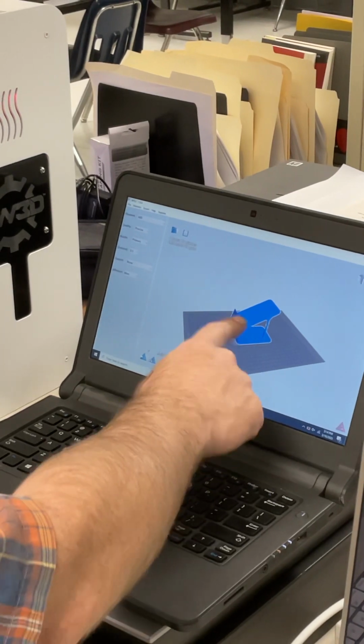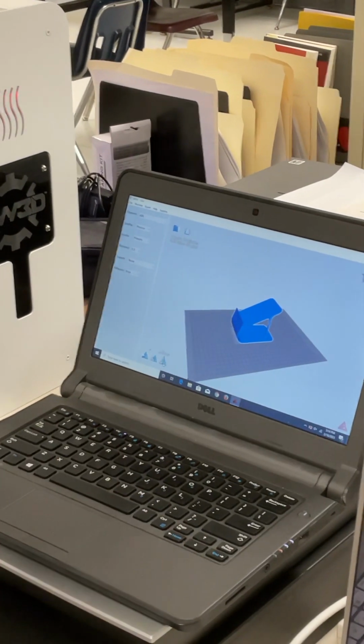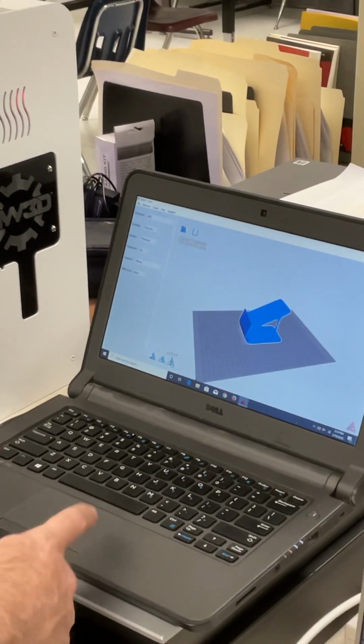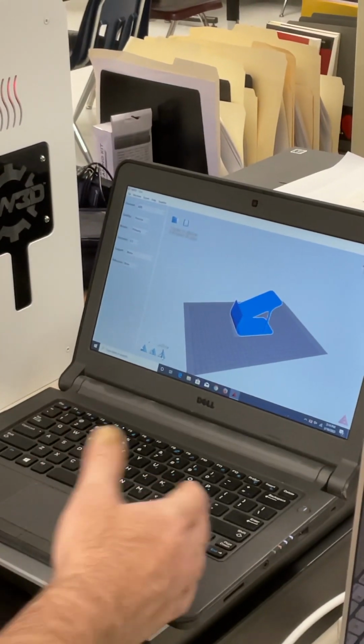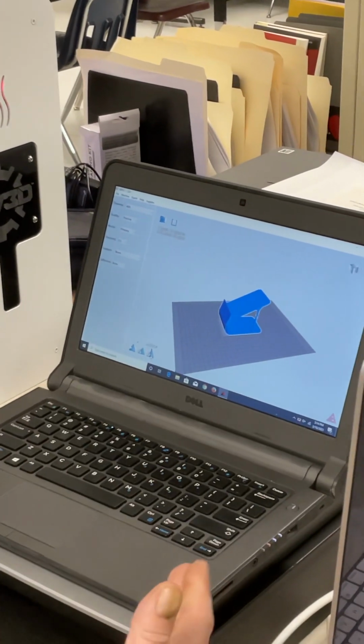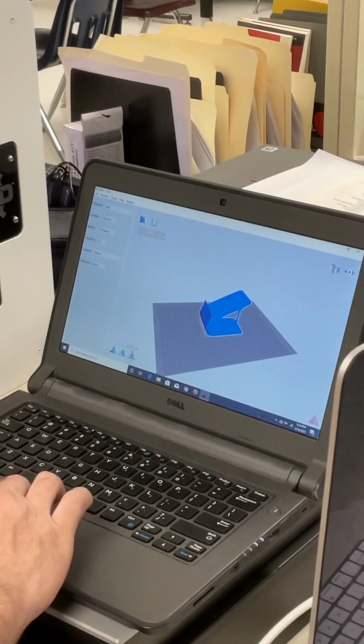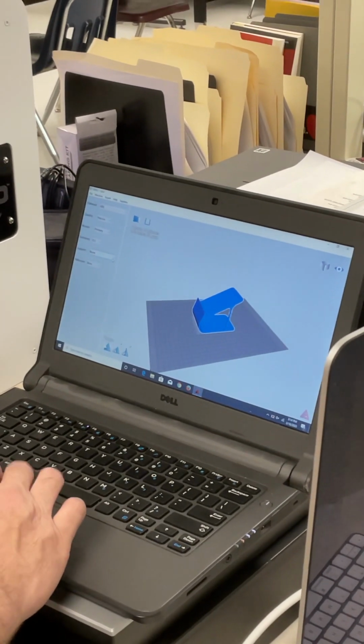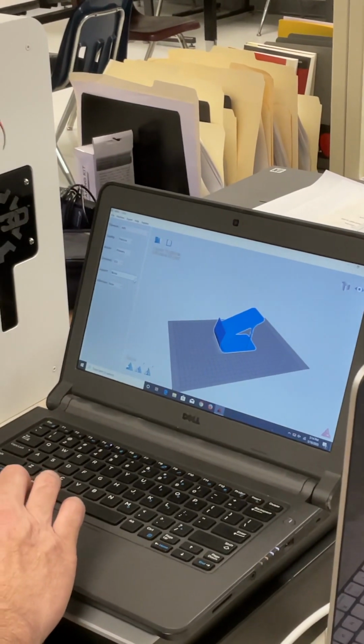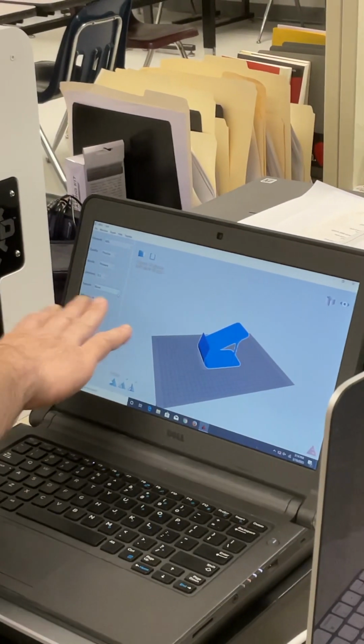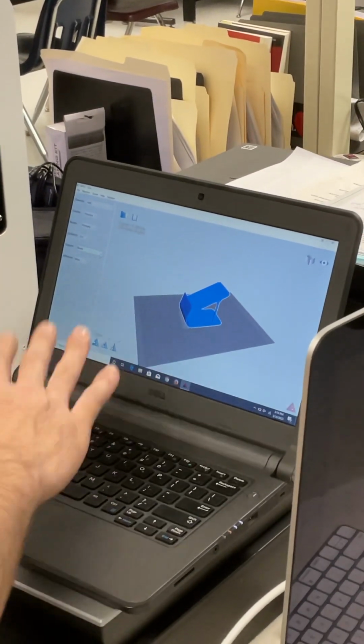Maybe not, because it's angled. So I don't think I need supports, but if it looks like it's gonna be printed out in midair, add supports to it. So when in doubt, always add supports and touching the build plate. I don't think I'm gonna need them for this, so I'm gonna have none, but remember, that's over here. So, and you can do that at any time, okay? I showed you at the beginning, but it doesn't have to be.